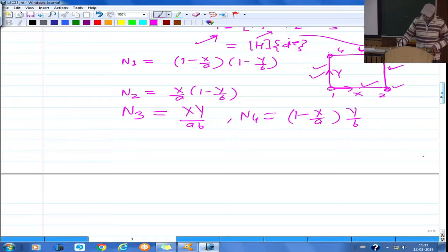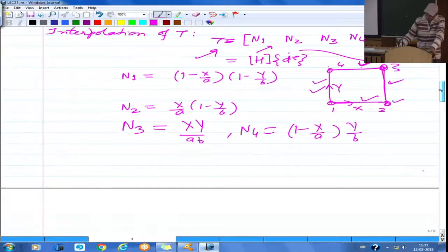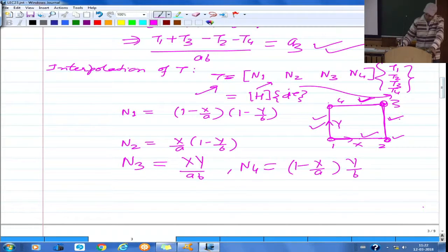In the same way you can go for the 8 noded rectangular element also. In the formulation and derivation of the shape functions, everything would be similar. But the drawback in this formulation is that every element has to be a rectangle in the physical coordinate space, and that is a restriction, because quite often in real problems the domains may not be regular. For the total domain discretization you need some general quadrilaterals, sometimes even with curved boundaries, and then obviously these elements are restricted in use.